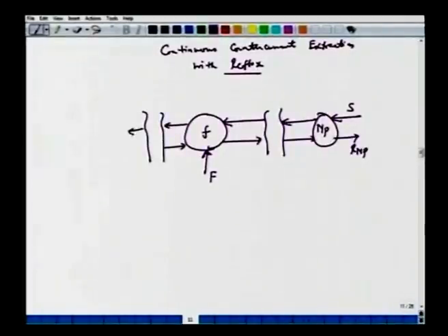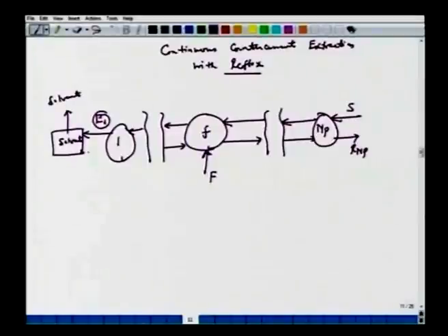Then we have another stage. Let's say this is the first stage, E1. We have extract E1. Now all we are saying is take this extract and separate the solute. So you have this E1 solvent separator here. Take this solvent and send it back. So this is your solvent here, and this stream is the solvent-free stream. Essentially you're trying to recover the solvent here and send it back like this.